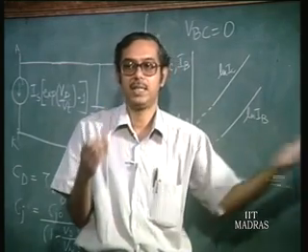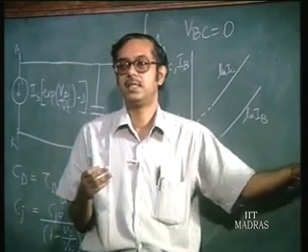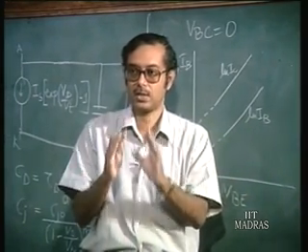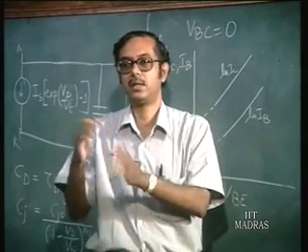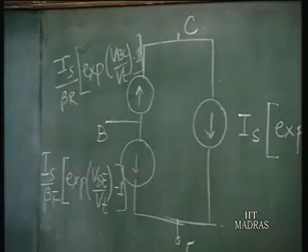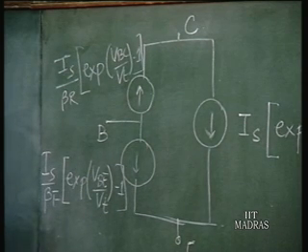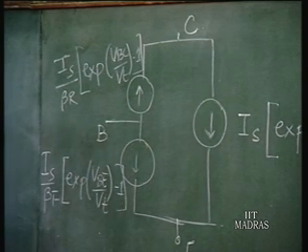So all this beta, beta f is dependent on the actual base width. So that is not a constant actually, but dependent on VBC also to some extent. So this model is just the basic model, and so we may have to do some corrections for other effects.